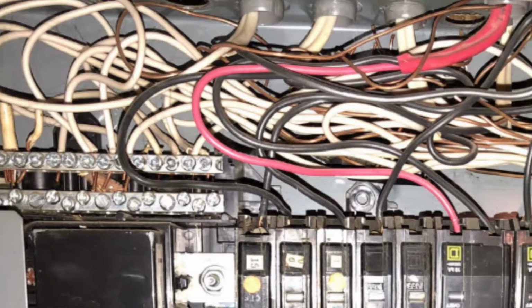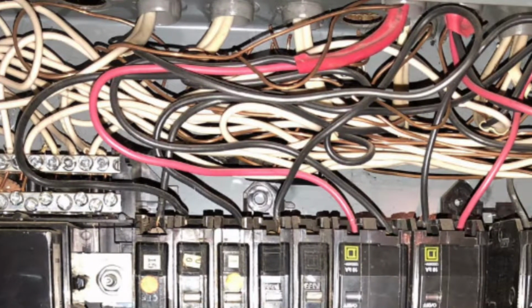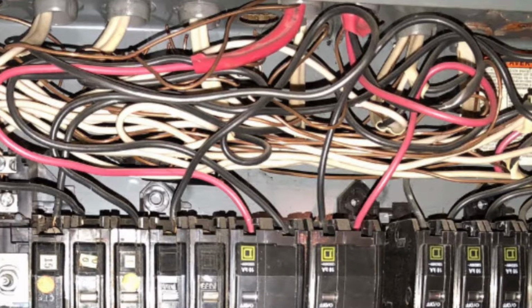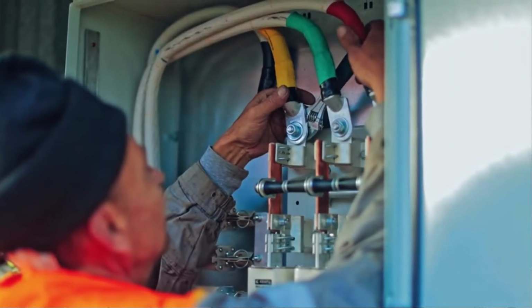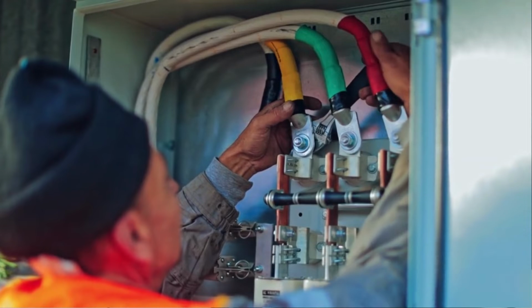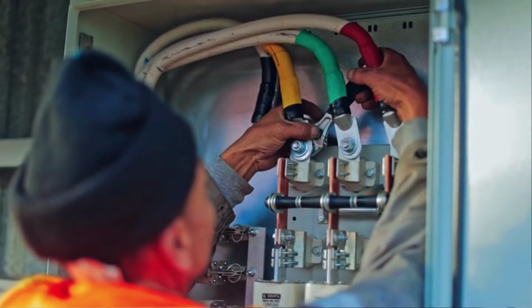The restricted approach boundary is an approach limit at a distance from an exposed energized electrical conductor or circuit part within which there is an increased likelihood of electrical shock due to electrical arc-over combined with inadvertent movement for personnel working in close proximity to the energized electrical conductor or circuit part. This shock protection boundary is the approach limit for qualified employees. The arc flash boundary may be greater than, less than, or equal to the restricted approach boundary.